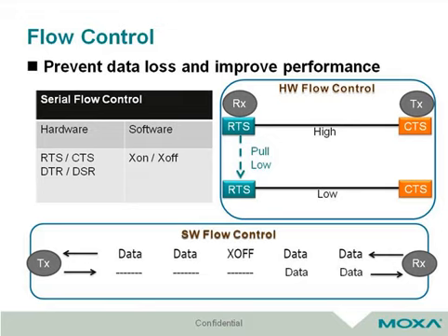For hardware flow control, if the data size in receive FIFO is over RBH, receiver sets its RTS to low, and the CTS at transmitter side will be low at once. So the transmitter will stop transmitting data. If the data size in receive FIFO is less than RBL, receiver will set RTS high to inform transmitter to start transmitting data.